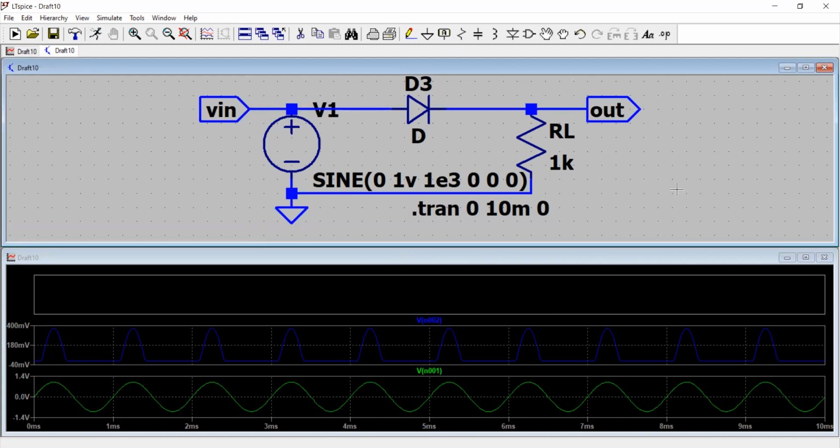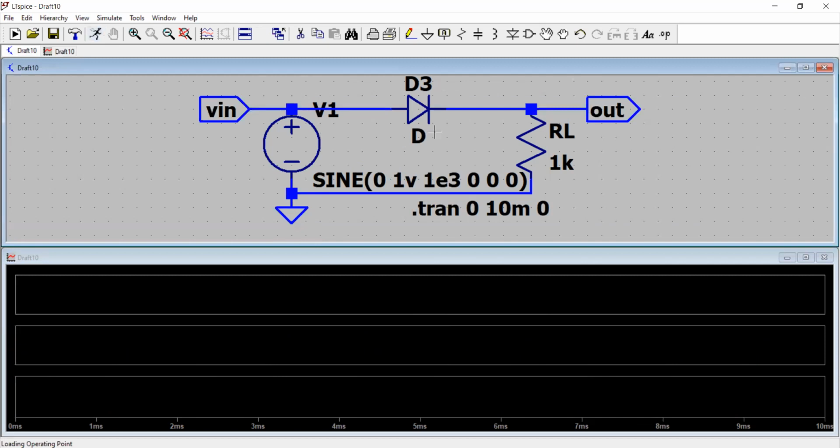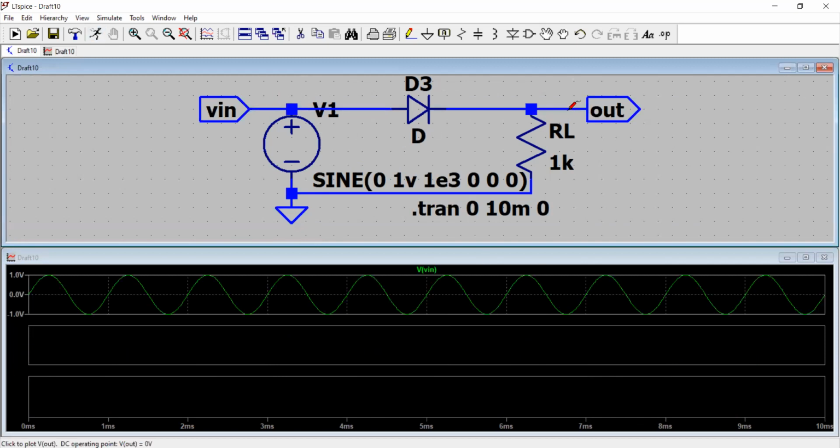Now when you simulate and you want to plot any net voltage, or current through the net or current through the component, you will be able to pick up and select the nets. So why not run the simulation again? And now you can just plot input, plot output. Output is on the same pane now. You see now the input is 1 volt and the output is about 340 millivolts. So the rest of the voltage during the positive half comes across the diode.